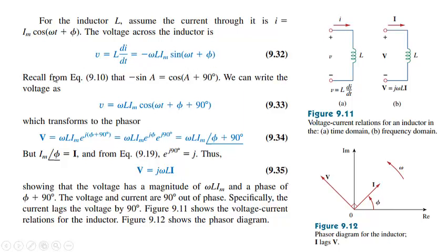Converting this to a cos again, we know that cos of a plus 90 will be equal to minus sine of a. We have to change the sine to cos, and we have to absorb this minus sign inside. So we use this formula to do the same. We change the sine to cos, omega t plus phi remains as it is, and the only thing is that we have to add plus 90 degrees over here. It comes out to be like this, which is the transform to the phasor.